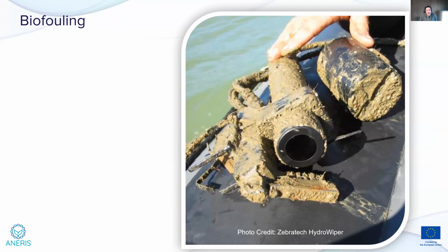One of the challenges that we have to deal with when we want to deploy an instrument for a very long time underwater is the problem of biofouling. Biofouling is all the biological mass that will grow. It depends on the depth of deployment, the amount of light, the turbidity, but in some locations, this is really dramatic. After a few days or weeks of deployment, your instruments can be completely wasted, filled with matter.